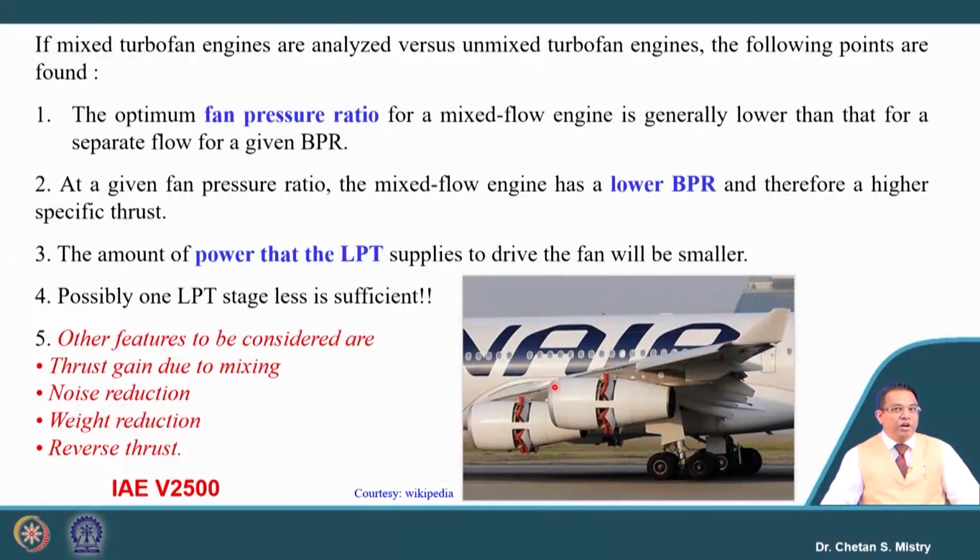What these people are doing here is, since the bypass duct is generating my thrust, they will open the duct, and through it they will allow the air to move in this direction. That acts as a reverse thrust, and that helps us in stopping the aircraft. So, many aircraft now, whenever you are sitting in an aircraft, if you have a chance to sit beside a window, you can see this kind of configuration. That is what helps in stopping or braking the aircraft.